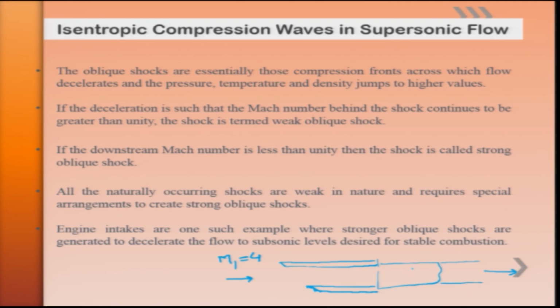The ramjet requires a proper combination of oblique shock waves and a terminating normal shock, which at the same time reduces the flow speed from supersonic to low subsonic, as well as compresses the flow from a high static ambient pressure to a higher pressure, such that as soon as it mixes with fuel in the combustion chamber, it can sustain a stable combustion for flying.